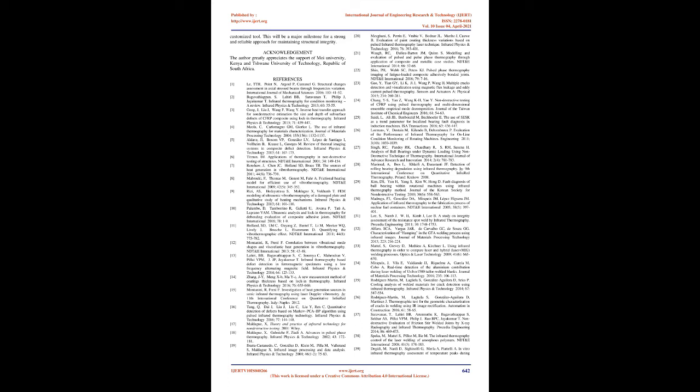The analyzed frequencies are presented in figure 9b. The extracted frequency from frictional temperature signature was 39.99 Hz. This was in good agreement with that acquired from the corresponding displacement as 39.99 Hz. Figure 9. Both beams excited at 40, A. Interface temperature contour, B. FFT of temperature evolution and displacement.